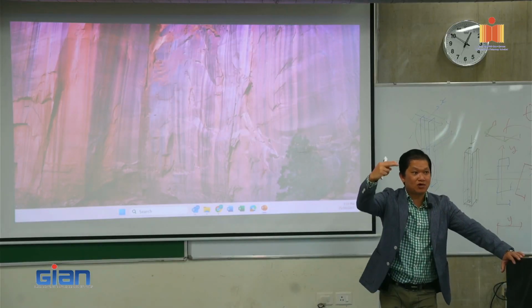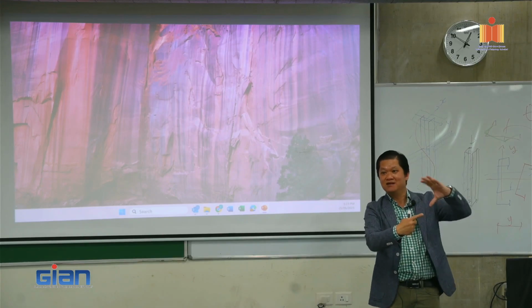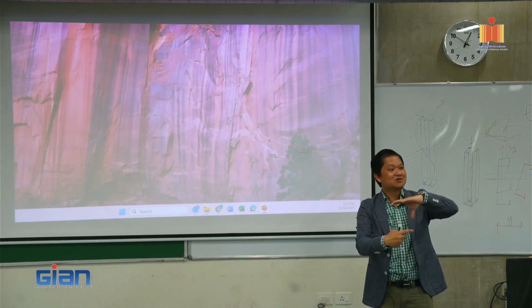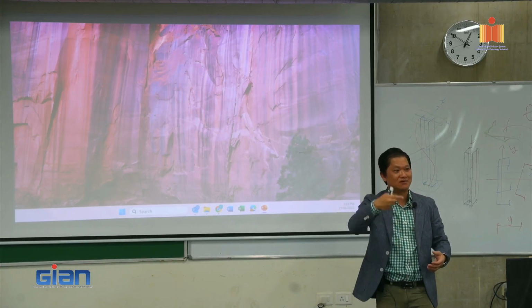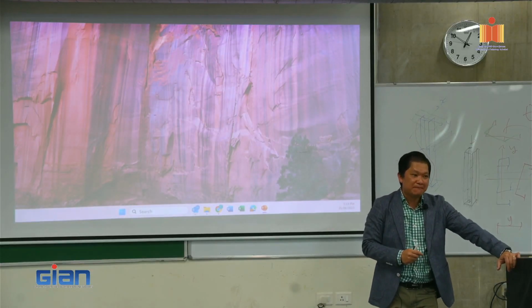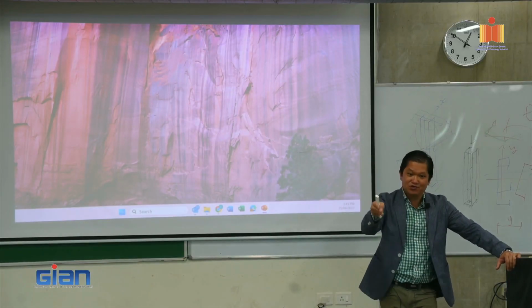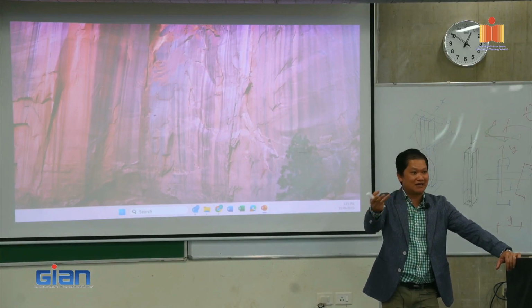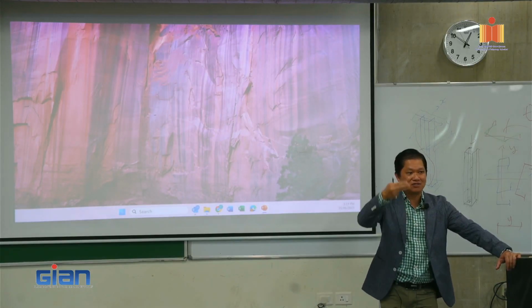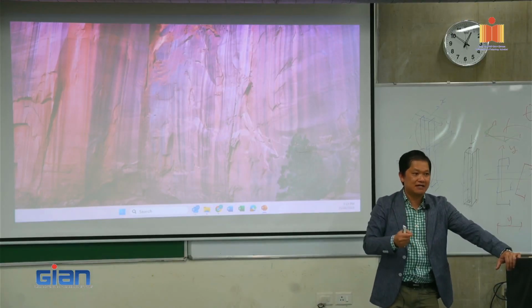So of course, when you put it on the top flange, it buckles this way. It's better than when you put it on the bottom. It twists like this one, right? So that's why it depends on the location of the lateral restraint. The standard will give you a different number, and you can just plug in. But it's a very good question. So it doesn't mean that you can put it anywhere in the middle and you get the same result. Of course, depending on the position, you can provide more restraint or less restraint.